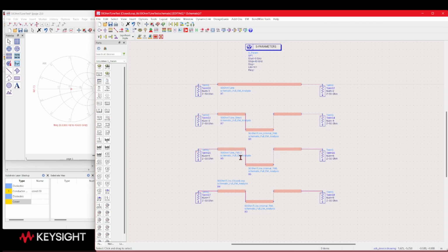Then I'm going to try TML0, which is a port we can use as an internal port, but all it does is essentially de-embed the fringing parasitic effect, the open-end parasitic effect, but really, we're going to get the full self-inductance effect. And then we'll look at the new addition to Momentum, which is the closed loop calibration for these two ports here. All right, so let's see what we get.